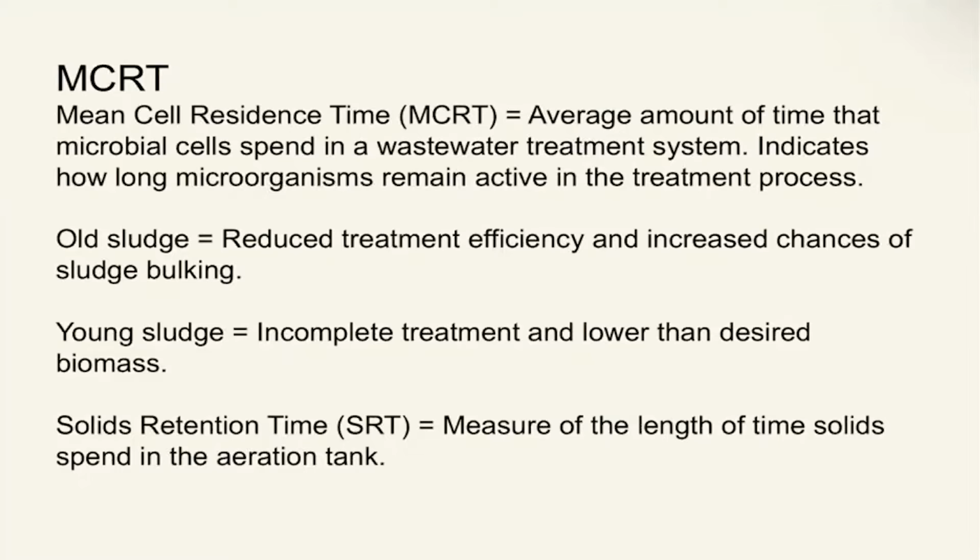It is then used to determine the rate of wasting and rate of reuse of solids that is appropriate from secondary clarifiers. It is important to make adjustments to the MCRT to maintain a balanced sludge age and ensure the microbial community is not too old or too young.